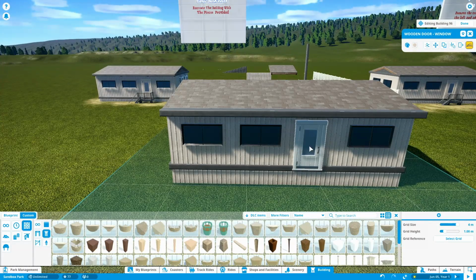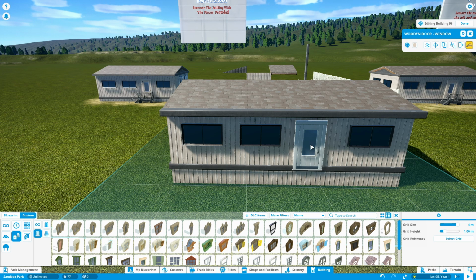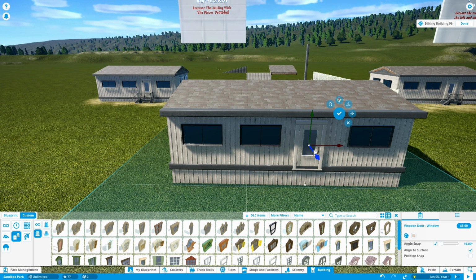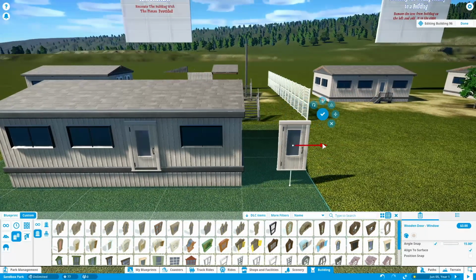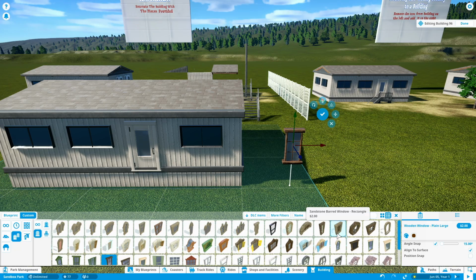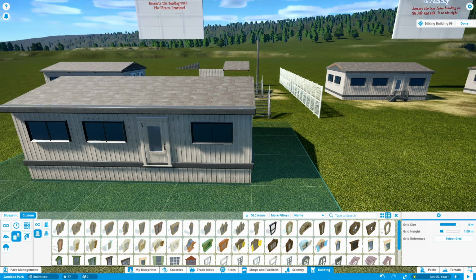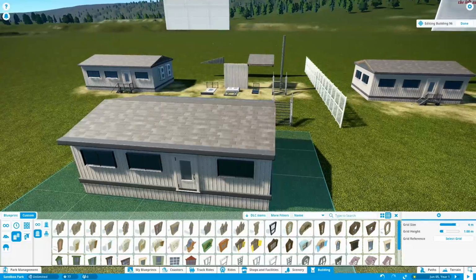Okay, so the other thing you can do too is if you don't have the piece lying around, if we go into Windows here, and all you had was this door up, you hit Control X on the door. So right now it's a door, but then if you go in here and start selecting Windows, it's going to turn into whatever window you want it to be. So that's another way of doing it if you don't already have the piece waiting for you.